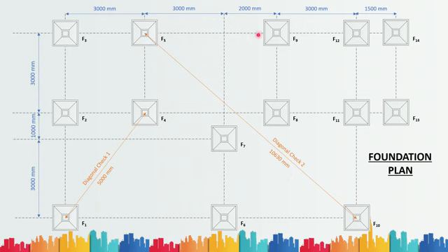So once you have plotted all these footings onto the site, if you take the tape and measure this distance, then it will give you improved accuracy. If this distance is not equal to 10630, then what you can infer is that somewhere the setting out of this or this foundation has gone wrong, so you can quickly redo this.